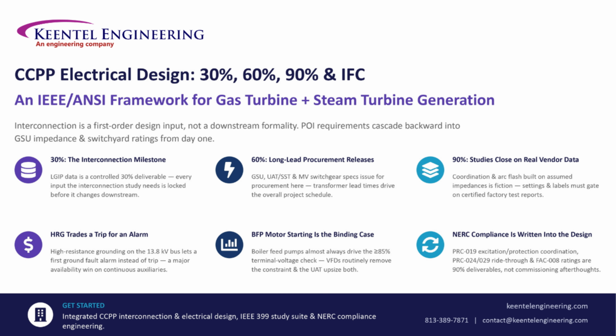High-resistance grounding on the auxiliary bus lets a first ground fault alarm instead of forcing a trip, which is a real availability win on continuous process equipment. And boiler feed pump motor starting is almost always the binding case for terminal voltage, which is exactly why many modern plants adopt VFDs. None of this works if NERC compliance is treated as an afterthought either. Excitation coordination, ride-through, and facility ratings have to be 90% deliverables, not commissioning surprises.